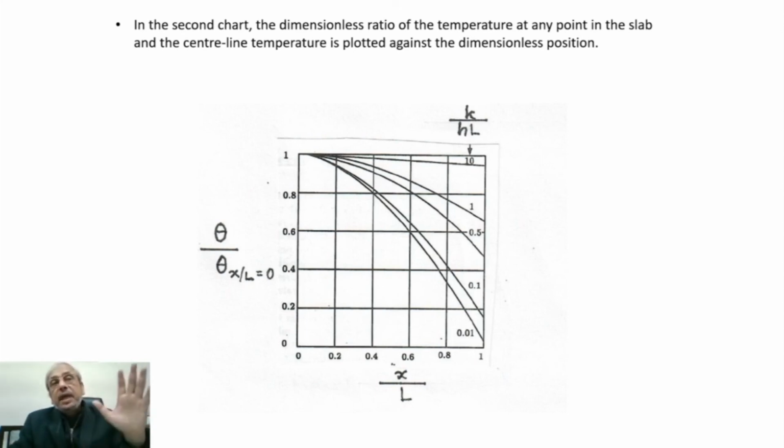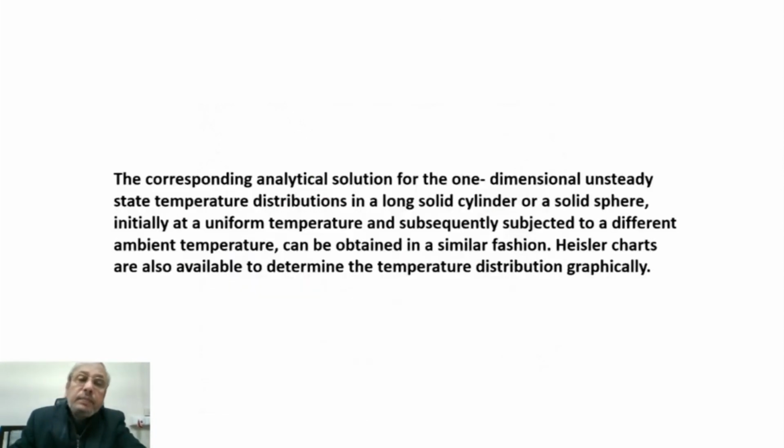in the sense that we start with a uniform temperature distribution on the slab, and after a given time, it is being cooled from both the sides. After a given time, what should be the temperature within the slab at any x location?